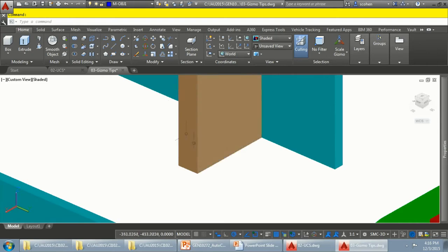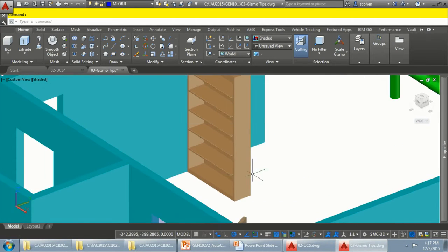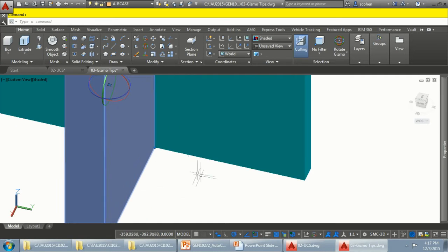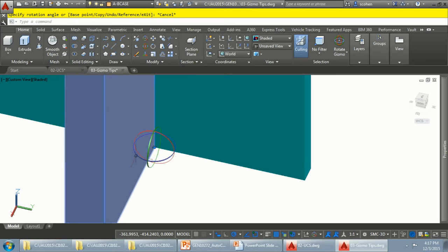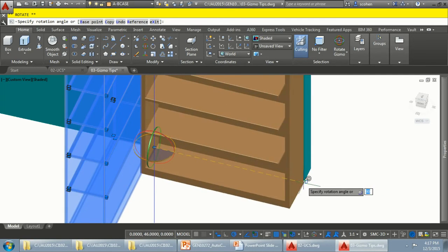All right, let's go ahead and look at this one here. Again, pretty straightforward. I got this bookcase. It came in as a part like that, but I want to actually rotate it to the actual wall. All right, so again, select. Scale was the last one I used, so I'll just right-click on that one and choose rotate. Now, I can simply hover here. Notice how it goes right to it. I didn't have to pick. Now, I always get these confused like crazy, but I'm going to pick, I think the blue one is the one I want. And no, it isn't. I always get the wrong one first. All right, so let's just pick this here. There we go. And so notice how this is pretty straightforward because it's perpendicular. It's 90 degrees.